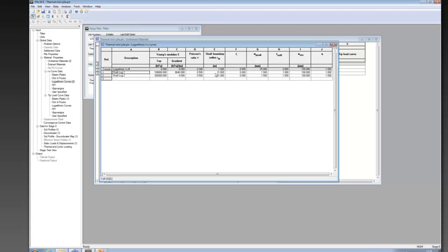And then we've got the shaft radius, the boundary radius where those shear stresses would reduce to 0. I should just note that that's quite a large number. People may be a little surprised that the area of shear around the pile is such a high number. However, just note that this would be the elastic range, whenever the shear stresses are still in the elastic range. Whenever the pile starts to fail, you would think of the radius of shearing being in quite a small range. However, this isn't the same. This large number is when you're considering elastic cylinders of shearing soil.